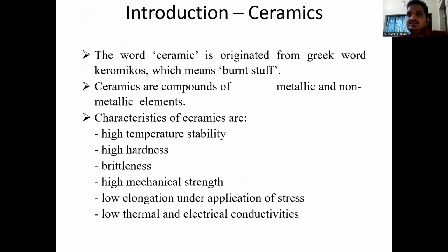When we are discussing ceramics, we have to understand the concept and the introduction involved in ceramics. The word ceramic originated from the Greek word ceramikos, which means burnt stuff. Ceramics are compounds of metallic and non-metallic elements. The main characteristics of ceramics are high temperature stability, high hardness, brittleness, high mechanical strength, low elongation under application of stress, and low thermal and electrical conductivities.